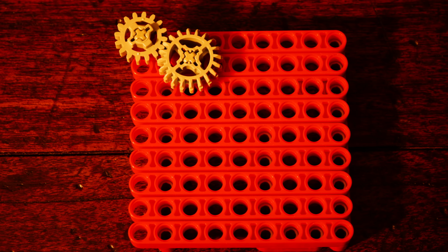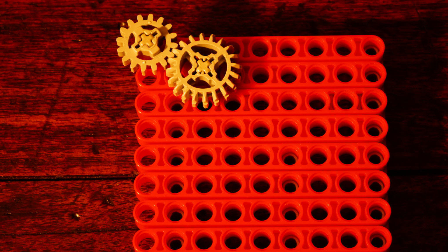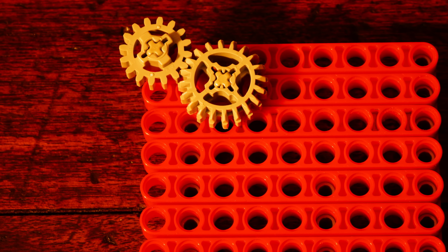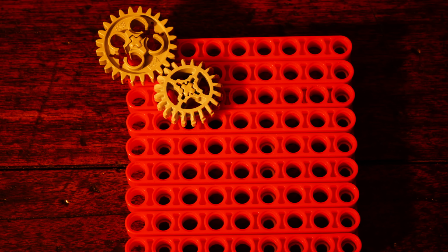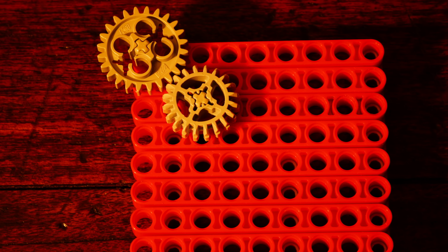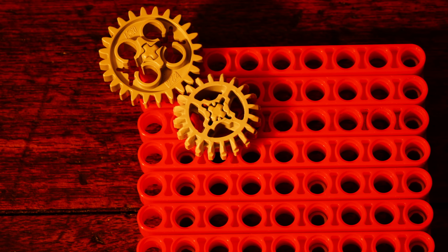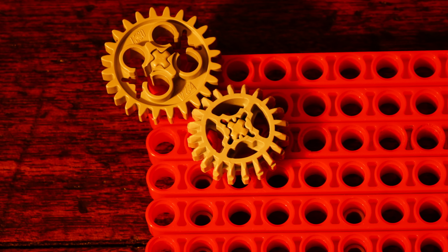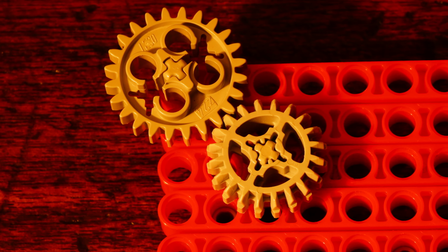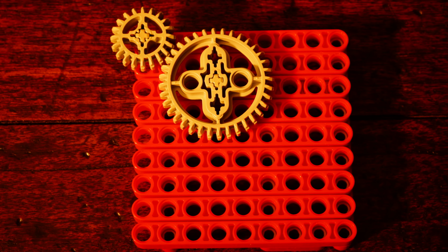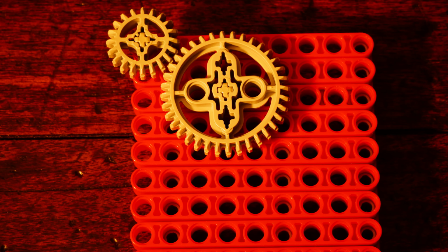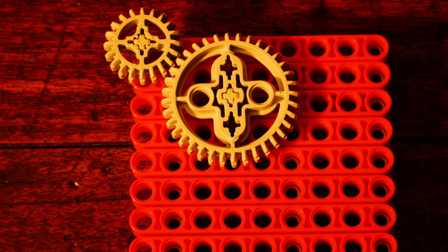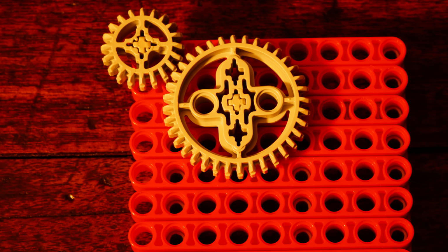For example, this 16-tooth spur gear powers a 20-tooth double bevel gear, in which the 20-tooth gear is positioned 2 studs to the right and 1 stud down from the driver gear. Or, if you wanted to create a gear train in which a 24-tooth spur gear powered a 20-tooth double bevel gear, the 20-tooth gear could be positioned 2 studs to the right and 2 studs down from the driver gear. Finally, if you wanted to create a gear train in which a 20-tooth double bevel gear powered a 36-tooth double bevel gear, the 36-tooth gear could be positioned 3 studs to the right and 2 studs down from the driver gear.